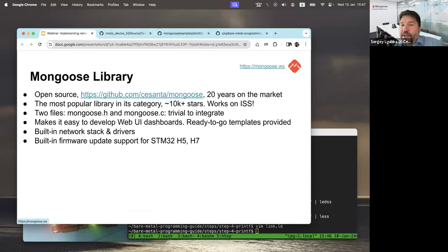So there is a question: can external memory like NOR flash be configured into dual bank and implemented for the case where the MCU flash is single bank only? Oh, I don't think so. All right. So if you have an internal flash in the MCU and an external flash, yeah, the thing is that this dual bank flash controls the mapping in memory.